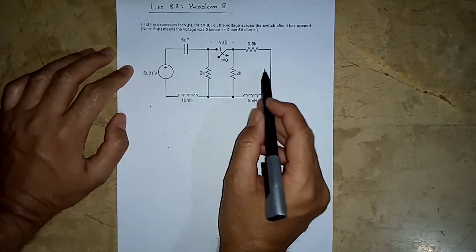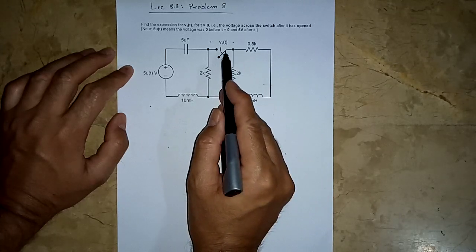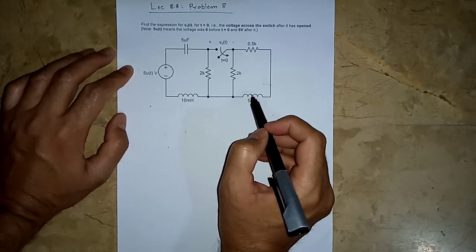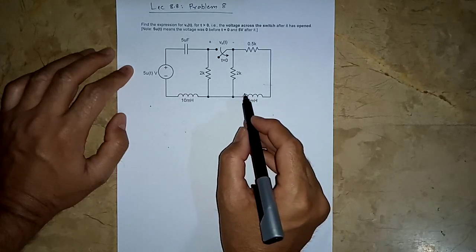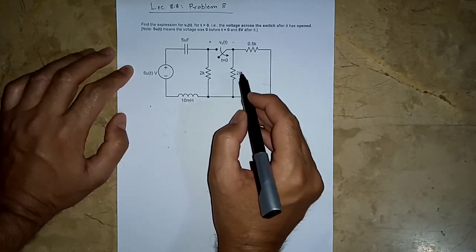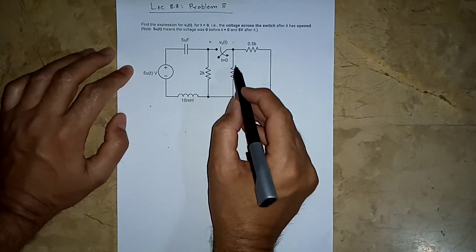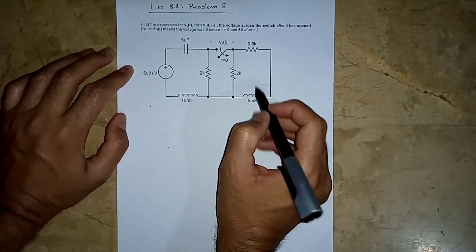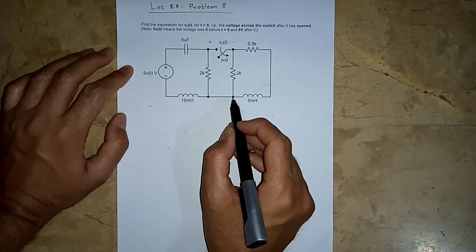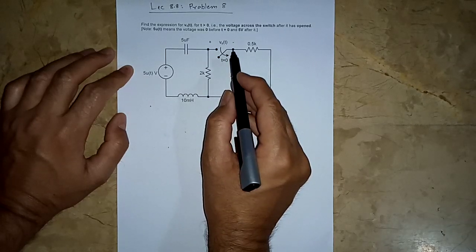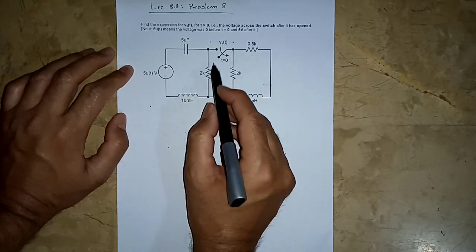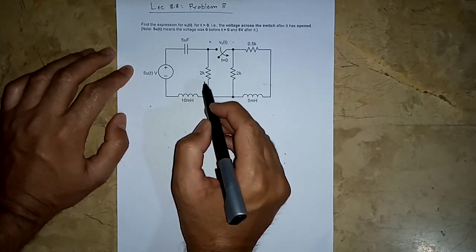Now, if you look at this circuit, when this was opened, there was no initial current here. So at t is equal to 0 plus, there will be no current as well. So no current, nothing flowing in here. So the voltage across this resistor would be 0. So it would be 0 here as well, and 0 here as well. So voltage across this is 0. If we take this as a reference node, then this would be at 0 volts as well. If this is 0 volts, this would be at 0 volts because there is no voltage across this. So whatever the voltage is across this switch will be the voltage across this resistor.